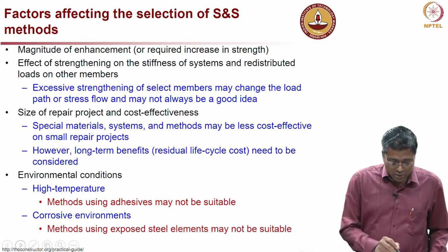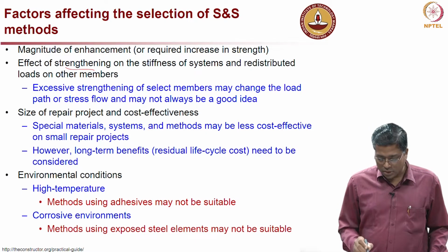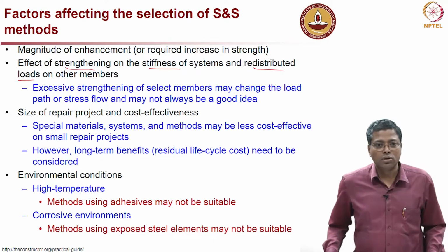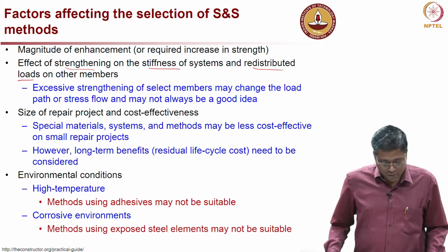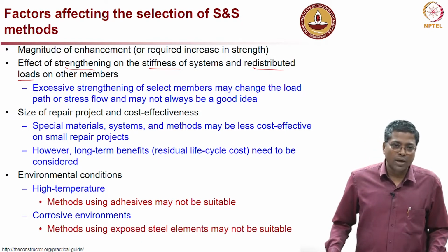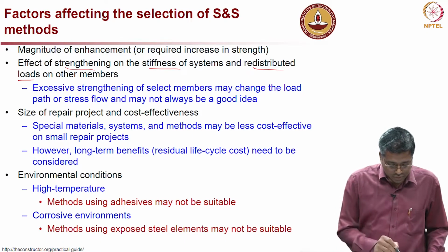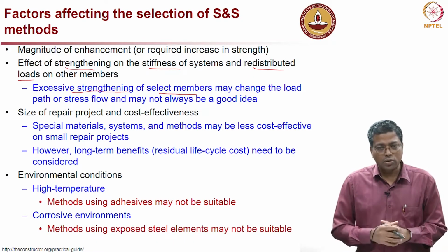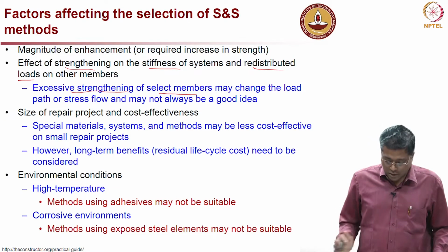Now, the effect of strengthening on the stiffness of the system and the redistributed loads onto the other members is also a very important factor which needs to be considered while selecting a stabilization or strengthening method. Excessive strengthening of select members may change the load path or the stress flow, and hence it may not always be a good idea.